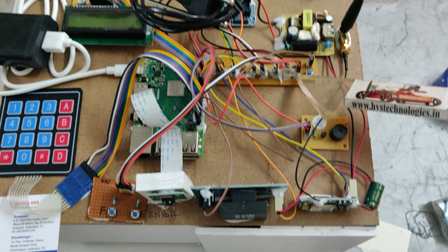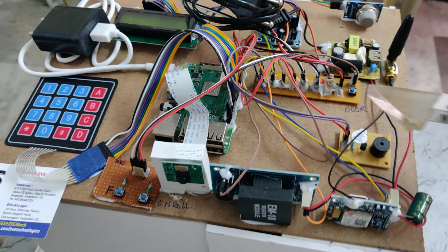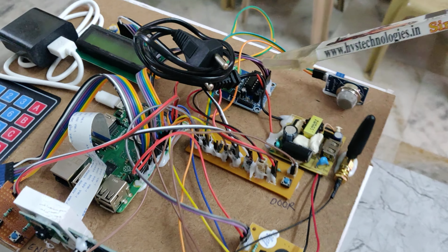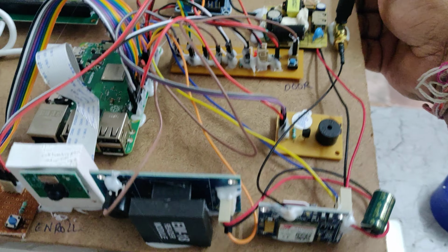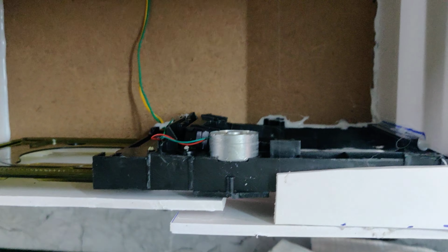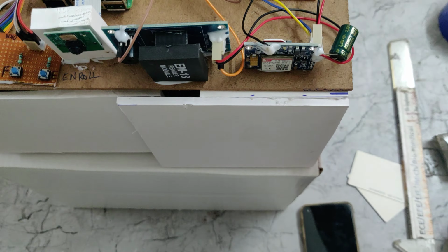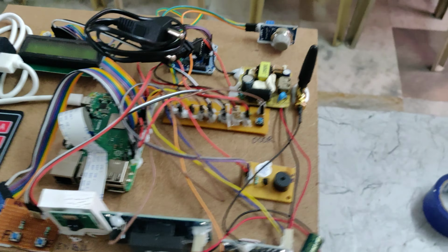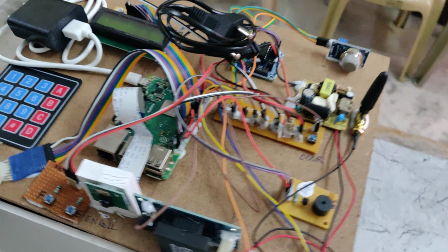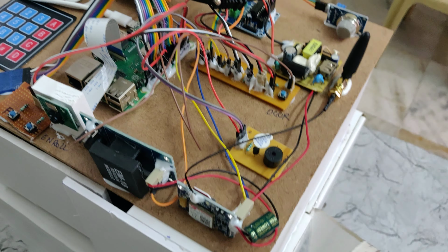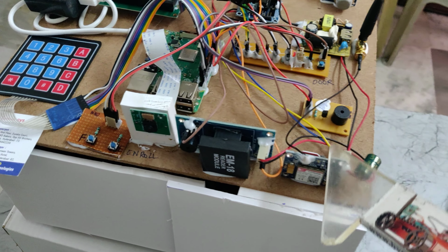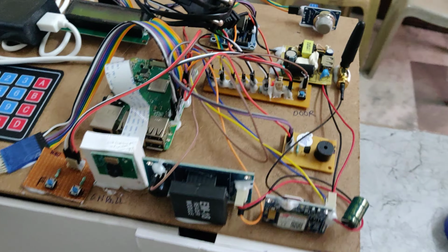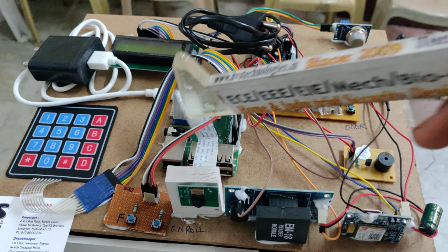This is the breadboard to distribute the 5 volts power supply throughout the input and output modules. This one is the L293D motor driver to control this door, which is attached to the rack and pinion mechanism. Inside this chamber we can see the DC motor attached to the rack and pinion mechanism to control the sliding door mechanism. This one is the MQ2 gas and smoke sensor, which will detect the gas levels inside this chamber. This one is a regulated power supply board to provide power to the GSM module and RFID reader. We are providing a separate power supply for these two and a separate power supply for the Raspberry Pi 3 B plus.